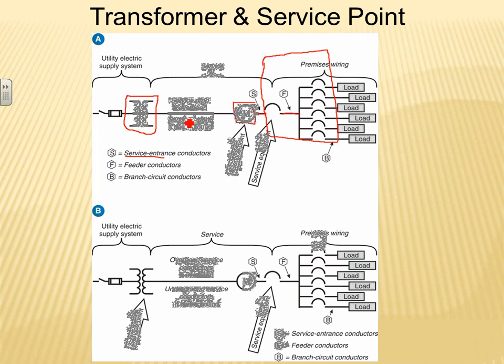So if you look at right here, from the meter, if you put the service point, which the utility decides where the service point is, right at the meter socket or MCC or termination box. So right in here, which is typically right at the termination box, from this side, this way, this is the responsibility of you as an engineer to design it, and the owner to maintain it. From here, this way, that will be the responsibility of the electrical contractor, the utilities to maintain it. So the demarcation point is very important.